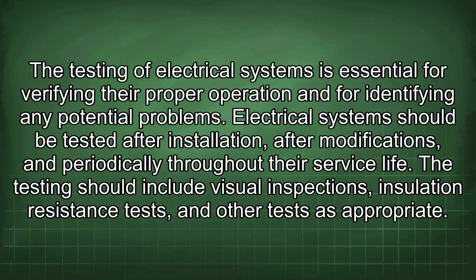The testing of electrical systems is essential for verifying their proper operation and for identifying any potential problems. Electrical systems should be tested after installation, after modifications, and periodically throughout their service life. The testing should include visual inspections, insulation resistance tests, and other tests as appropriate.